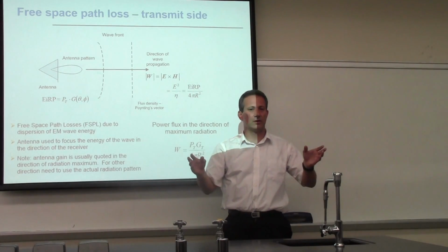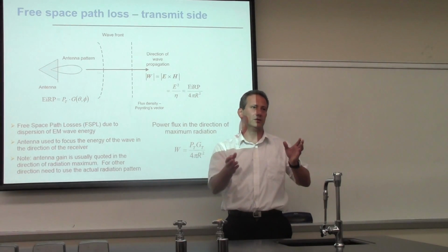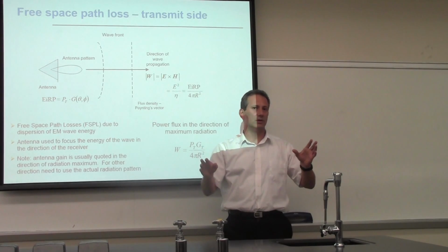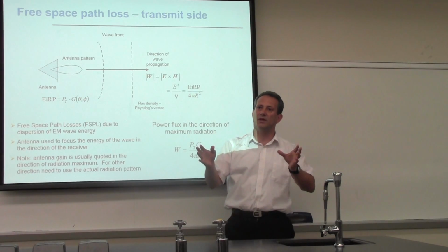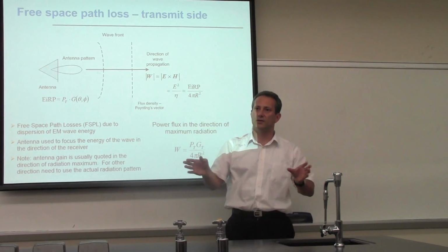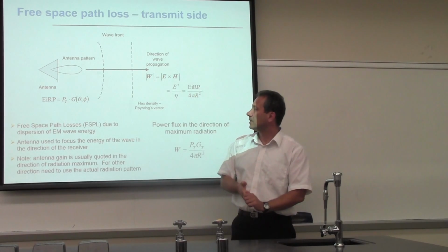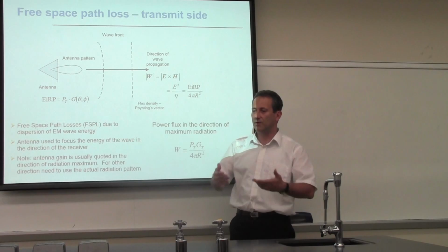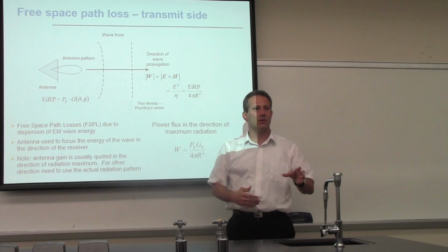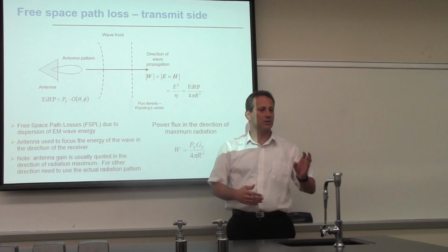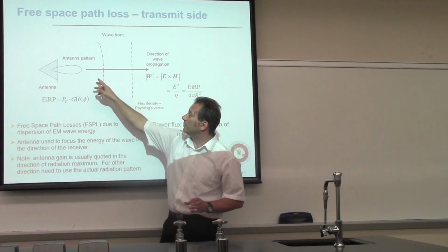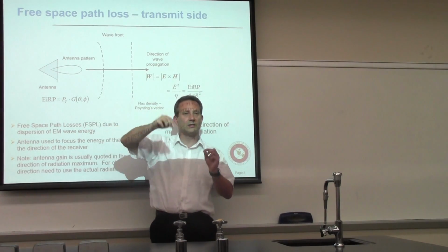Now, radiating power is a function of two angles. It is a function of both azimuth and elevation, because as we know, antennas are spatially selective devices. They radiate differently in different directions of space. Now, a lot of times, implicitly when we say the EIRP of this transmission is such and such, this is the effective radiating power in the center of the main beam.